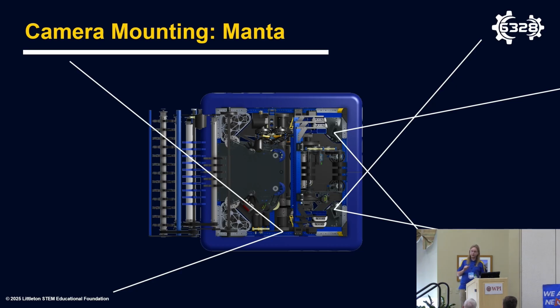And the tricky thing there is the April tag can be in very close proximity in front of the robot. So our visibility is provided by two cameras that are actually pointing inwards to have this nice overlapping field of view where we can see tags very close. But we still wanted to provide a larger field of view when further away, so the cameras are spread out enough that we can do that.